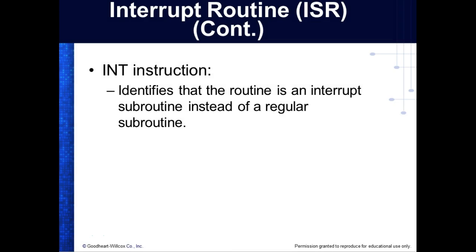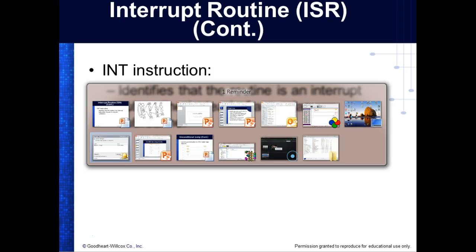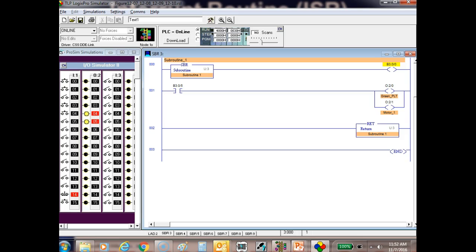The INT instruction identifies that the routine is an interrupt subroutine instead of a regular subroutine. So we have an INT instruction. Now let's see if RSLogix supports that. What group would it be in? Program. Yeah, program control. Is the AFI in the program control? In RSLogix, just because it's not here,